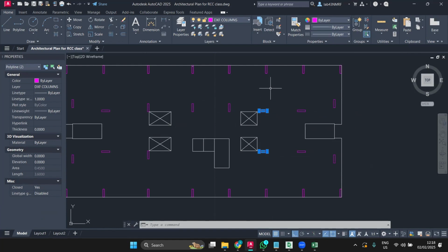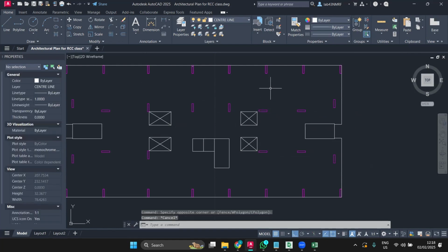Why do you want to change it? Just now I told you, in order to get the stiffness, you need it in the longer direction. It is good that fortunately some of the columns are in the longer direction, right? Or else for the longer direction, you need to depend on only the walls. Correct? Yeah. Say, copy in the new CAD actually.